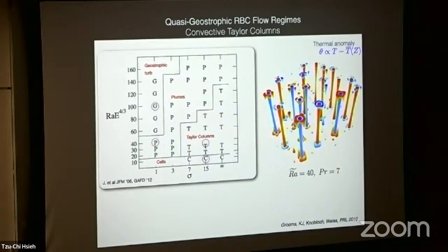So how do they occur? It's really an instability of the thermal boundary layer. We know that even in non-rotating convection, if you drive the fluid, eventually the thermal boundary layer, which has an unstable gradient, becomes unstable and you develop a blob-like instability. In the rapidly rotating limit, we get an unstable boundary layer, and fluid descends from the boundary layers, and they actually synchronize.